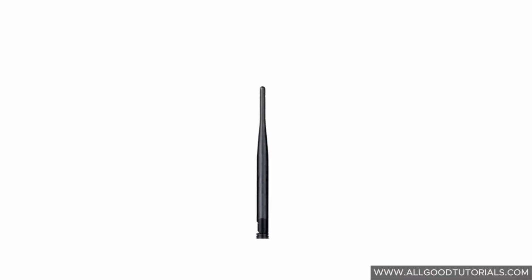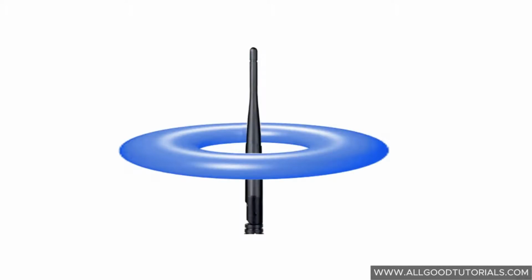Many wireless routers today have advanced features such as beam forming that use multiple antennas for both transmitting and receiving signals. These antennas are simple omnidirectional antennas like I'm showing here, which we sometimes call rubber duckies or whip antennas. When the signal radiates out from these antennas, it doesn't radiate equally in all directions, but rather forms this donut type shape where the signal is stronger as it radiates to the side of the antenna than it does radiating up or down from the antenna shown in this picture.